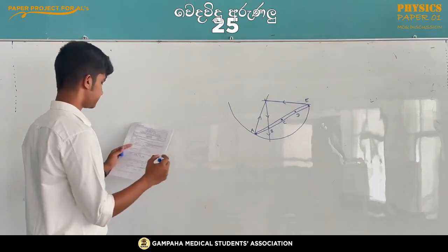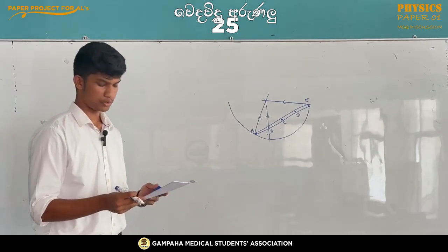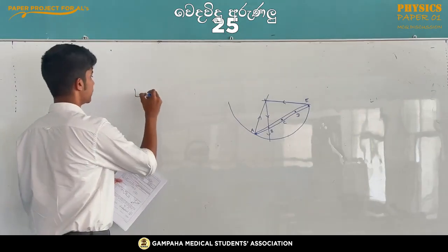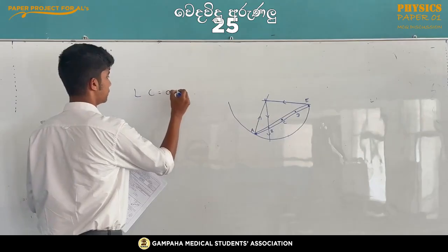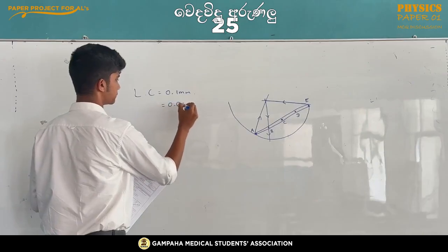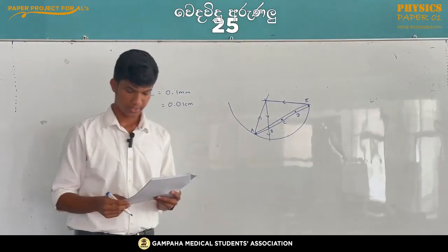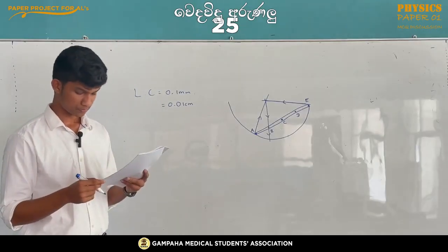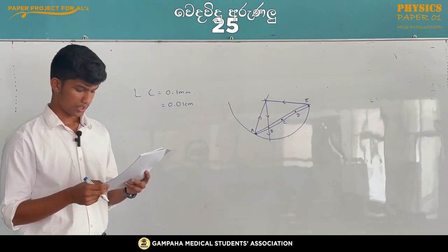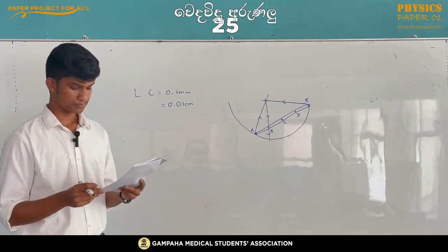You can see that 0.9 centimeters have been divided into 10 divisions, and then you can get the least count as 0.1 millimeter or 0.01 centimeters. So using this, you can look at the second figure, and you can see that the sixth division of the Vernier scale coincides, and since you are measuring the depth, once again you don't have to consider the zero error.